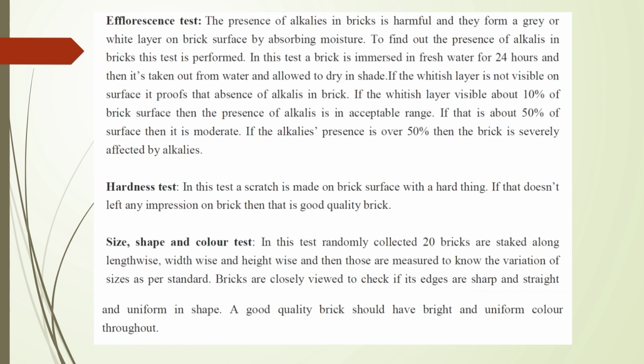Efflorescence test. The presence of alkalis in bricks is harmful and they form a grey or white layer on brick surface by absorbing moisture. To find out the presence of alkalis in bricks, this test is performed.